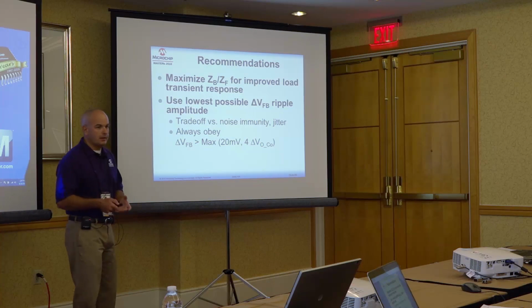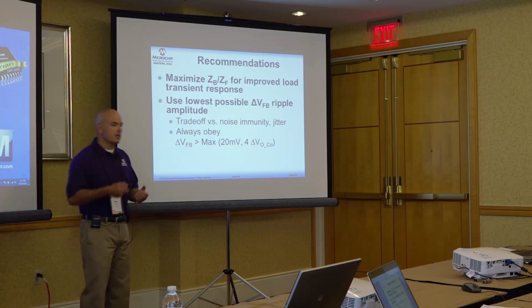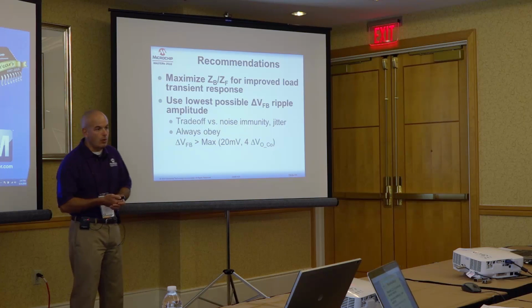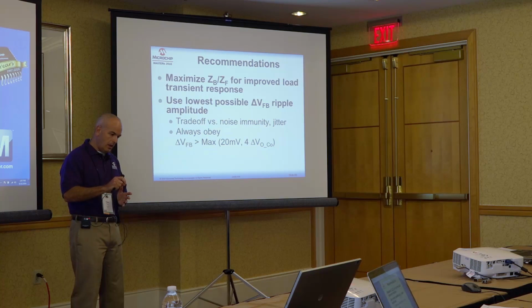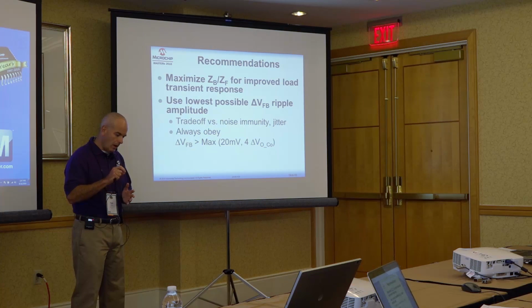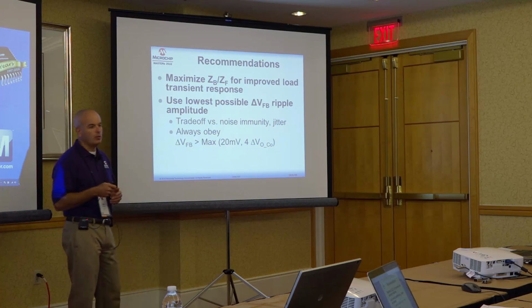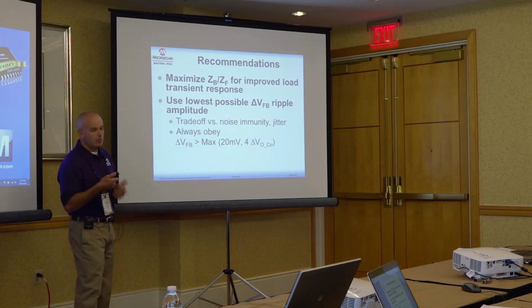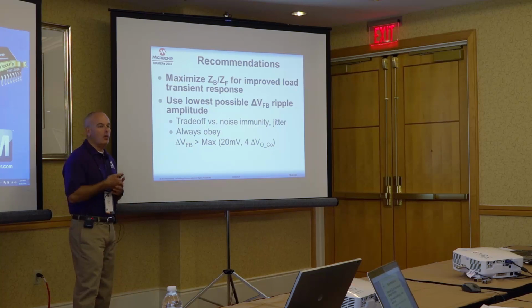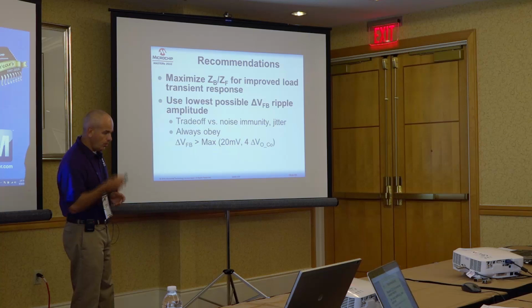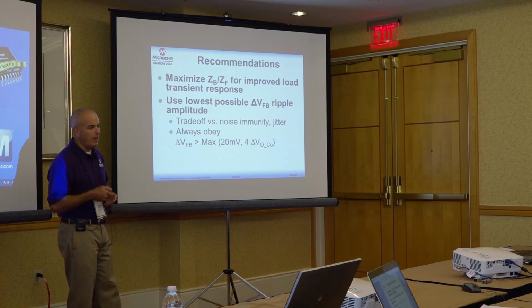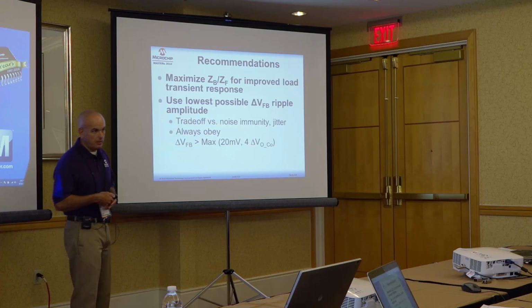Don't forget that constant on time is a ripple-based control, so it's very sensitive to noise and jitter. So if you are lowering and lowering the feedback ripple amplitude, you will end up being more jittery or more noisy. And in any case, you always have to keep in mind stability criteria.